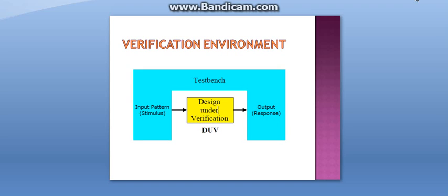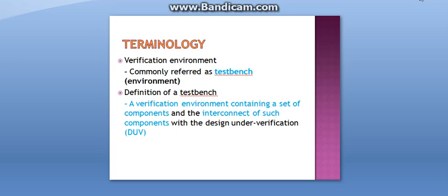In verification, a testbench environment is commonly used. It contains a stimulus generator, that is the input pattern, then the design under test, that is DUT, and response checking, that is the output. The definition of a testbench is a verification environment containing a set of components and the interconnect of such components with the design under verification. Components such as bus functional models, bus monitors, and memory models.